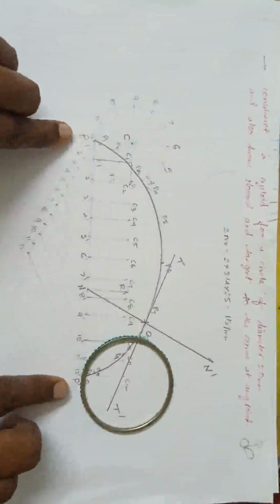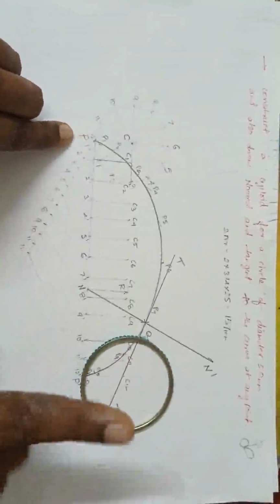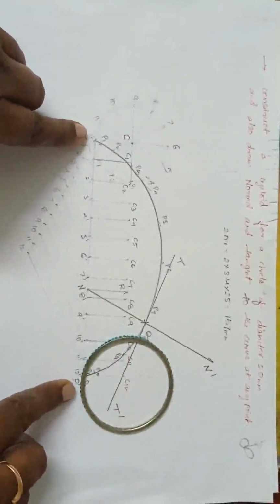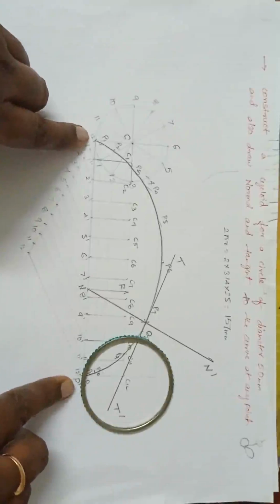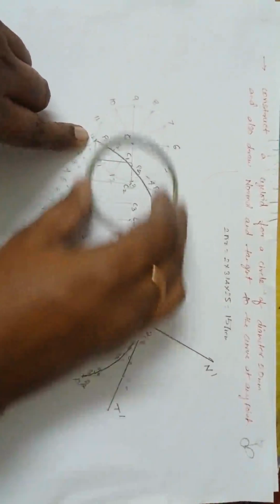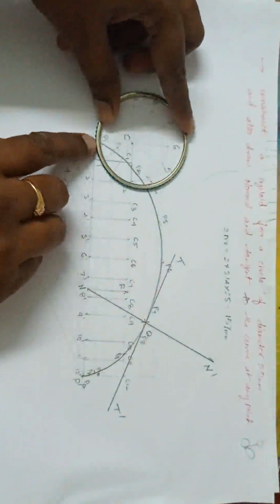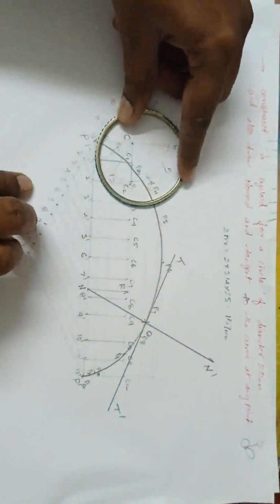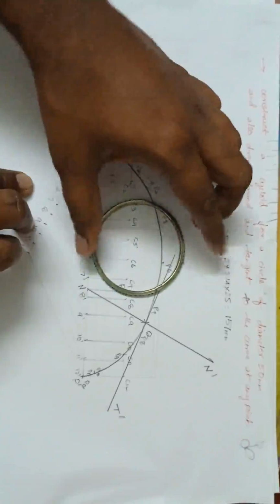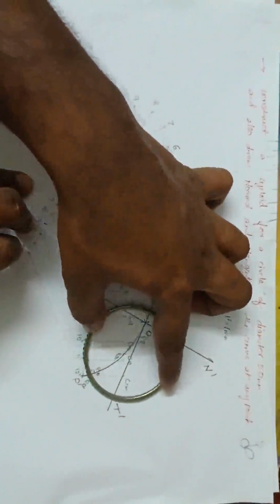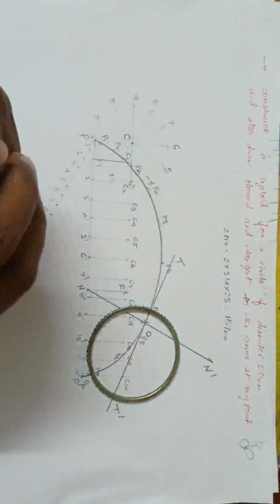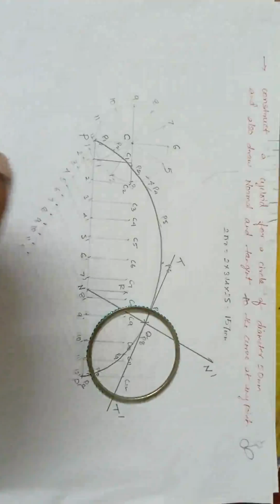After completing one revolution, the point P touches the ground again. We assumed that the distance traveled is 2 pi r, the circumference of the circle, and we traced the point P. Stage by stage, while rotating, we traced the point P like this for one complete revolution. That is said to be a cycloid, when it is rolling on a flat surface.